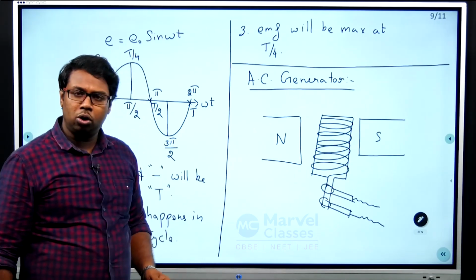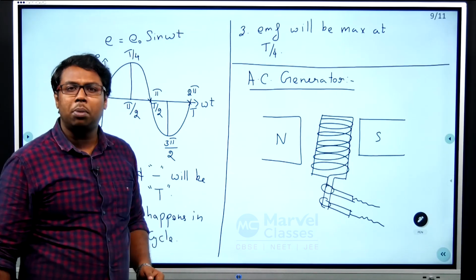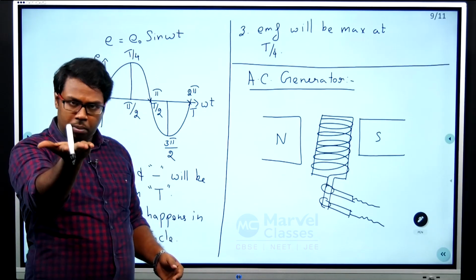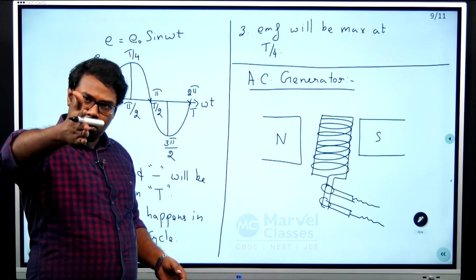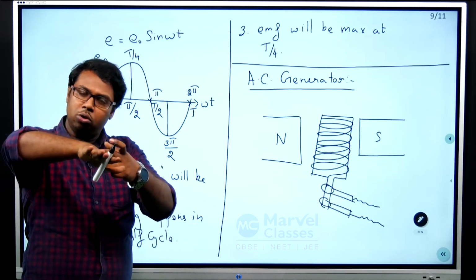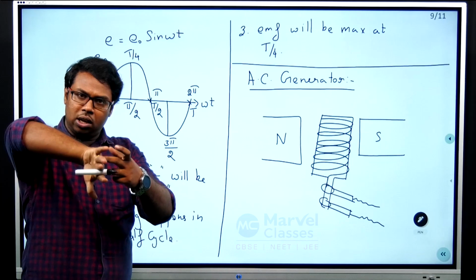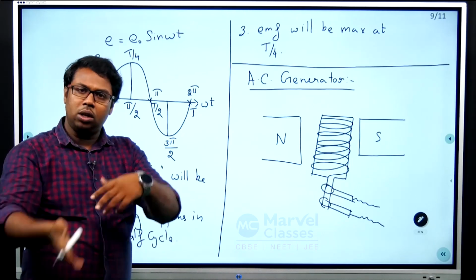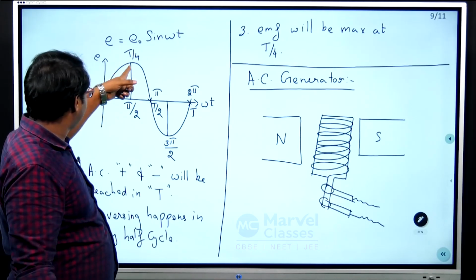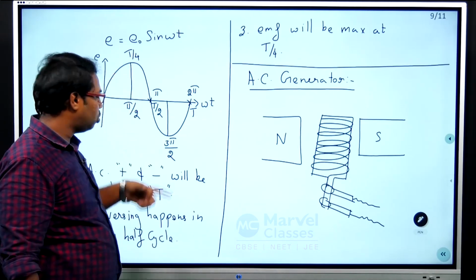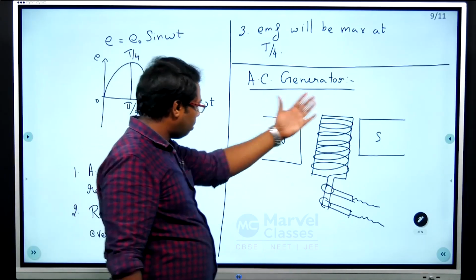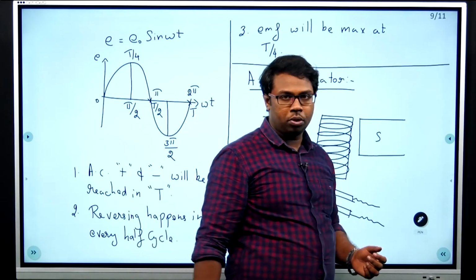An armature coil is going to rotate and the armature coil will produce a maximum AC current when your armature coil is in the plane. Only when your armature coil is like this, it is not going to produce any EMF. Again it rotates, it produces EMF. Again it rotates, the EMF goes to 0, and again when it rotates, the EMF comes in. Like that, the EMF from 0 reaches the peak value, again it comes to 0 and it goes to the peak value on the opposite side. The same thing is happening in your AC generators too.